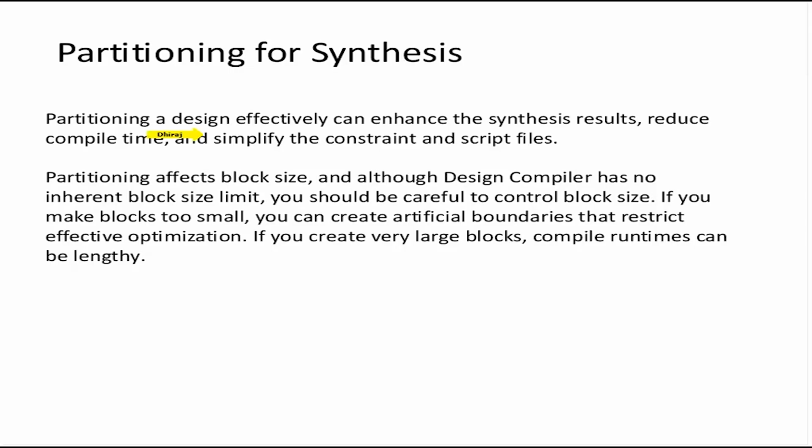So, partitioning a design effectively can enhance the synthesis results. It can reduce the compile time. Compile time here means the synthesis time, and simplify the constraint and script time. Partitioning affects block sizes. Although Design Compiler has no inherent block size limit, obviously as we keep on increasing the complexity in RTL, the compile time will keep on increasing. So there are again two extremes.